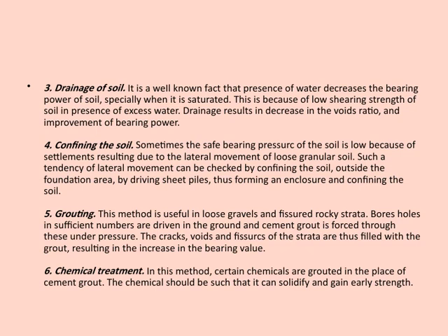Let's now discuss some important methods to improve soil-bearing capacity. First, drainage of soil is a well-known technique. As many of you know, water presence in soil, especially when it's saturated, significantly decreases its bearing power. This happens because excess water reduces the soil's shearing strength. By implementing proper drainage, we can decrease the void ratio and, as a result, enhance the soil's bearing capacity.